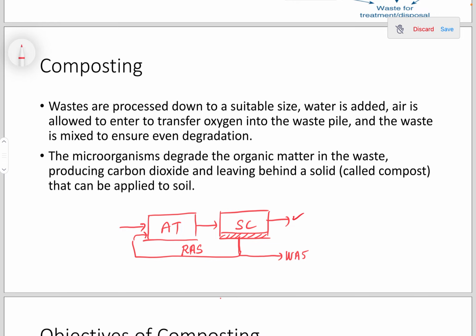Now, why do we have to waste? Remember, we have to control the F/M ratio. We have to keep the bacteria under starvation. We have to not let them eat everything. I remember we asked the engineer at that time, he told me that F/M is almost 0.1, and that is good. F/M, remember, we have too much microorganism and less food, which means that he is recycling activated sludge more.